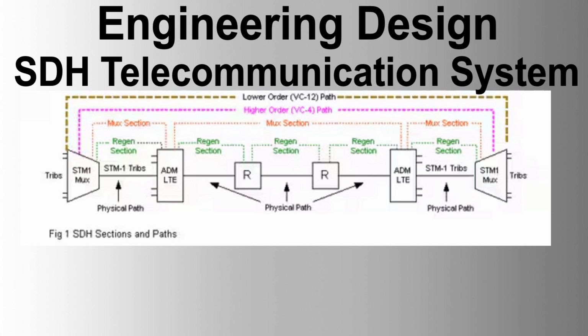25% expansion space capacity provided in cabinets and racks for cards, terminations, and termination space in the cabinets, but no hardware supplied. Systems, servers, workstations spare capacity. Maximum of 30% system memory RAM utilization, under maximum load, for all servers and workstations. Hardware upgrade space slots to install a further 50% memory which the system can use.